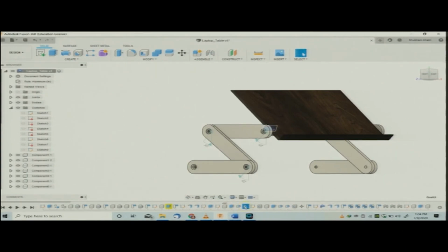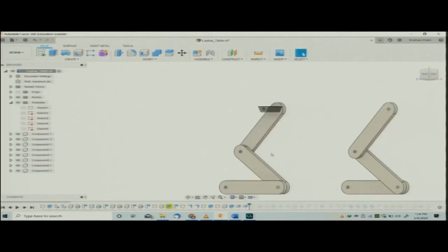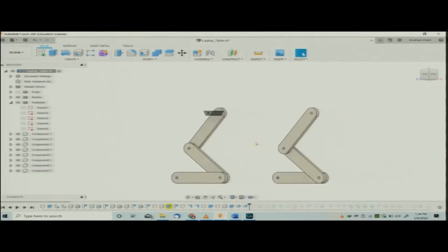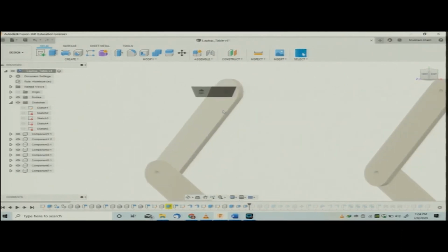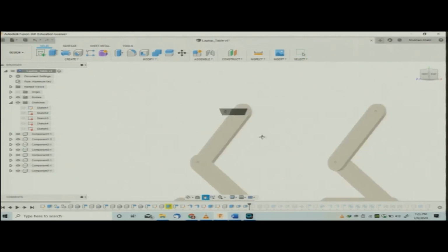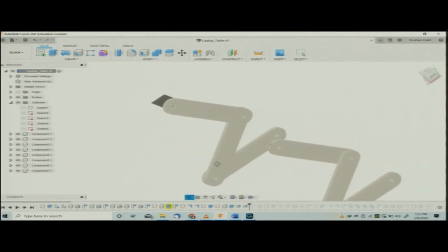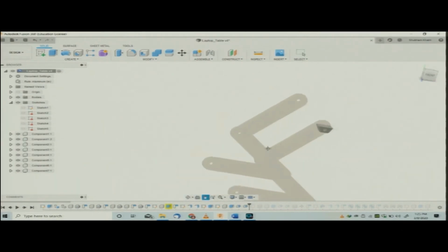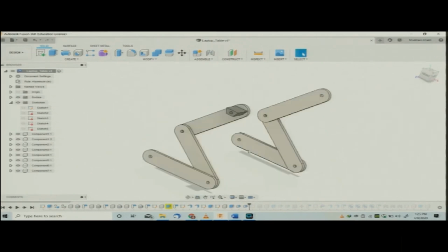For instance, if I click on this specific step and right click here, then I come to roll history marker. It is showing the history marker at this stage. This was the status of the drawing that I was making. So, we can make changes here as well. Whatever changes I make here would again happen in the final assembly.